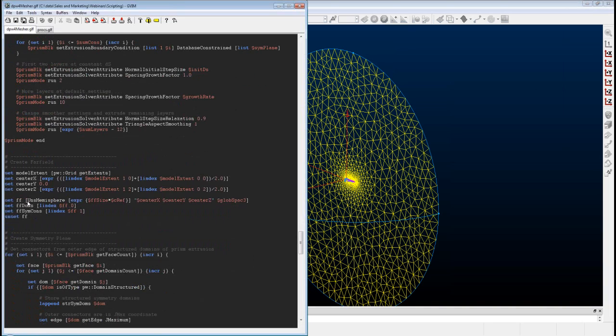So creating those far field domains, we just use the procedure that I mentioned early on. This procedure creates those 2 hemispherical far field domains based on the diameter. In this case, the diameter is a function of the reference chord length of the aircraft. We feed it the center point of that sphere, as well as the grid spacing value in the far field.